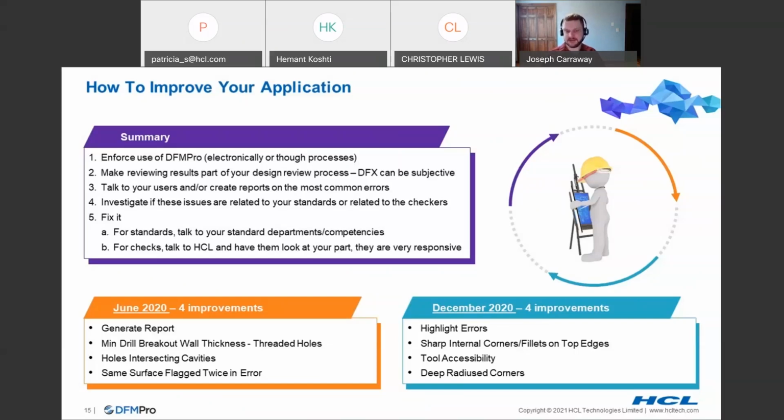There's a lot of discussion, even in my career early on, that you have to have chamfers on the outside of a part, radius on the inside, never radius on the outside. But as technology progressed, those conversations are no longer nearly as applicable as they were 10, 20 years ago. Additive manufacturing is also changing this, so you can't apply manufacturing rules to additive manufactured parts. You have to have correct standards for these.